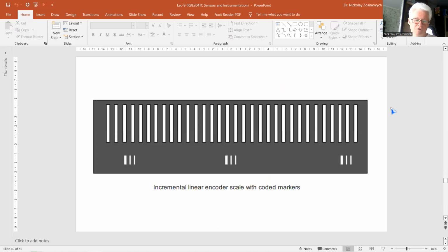Serious disadvantages of an absolute encoder are its limited resolution, the large number of output sensors, and the consequently high price. A much better resolution is achieved by the incremental encoder, of which this figure shows a typical example for linear displacement. It has only one track consisting of a large number of transparent slots. In the angular type, these slots are arranged radially along the circumference of the optical disc.